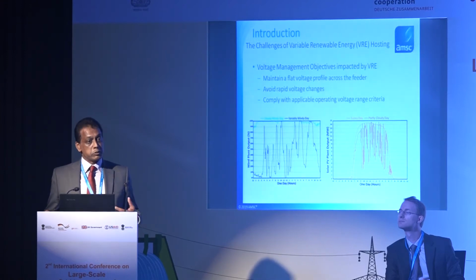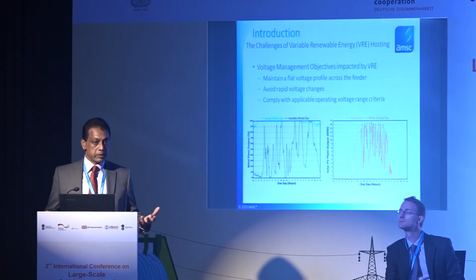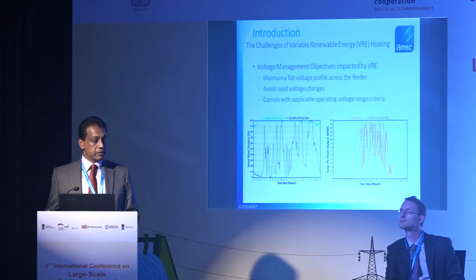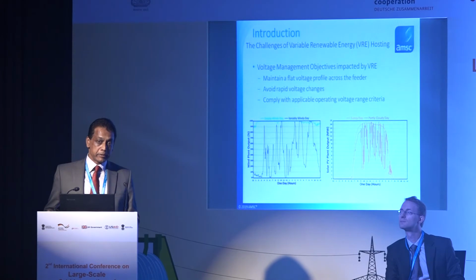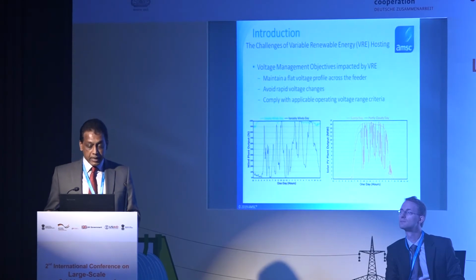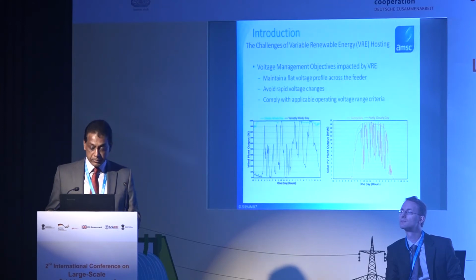Now you are trying to use those feeders to integrate new forms of energy generation, renewable energy, be it rooftop solar, community wind, community solar, small, medium, large plants that need to come in. The first opportunity is to maximize the capacity of that existing feeder, while also maintaining the normal reliability requirements, normal supply quality requirements for your customers.